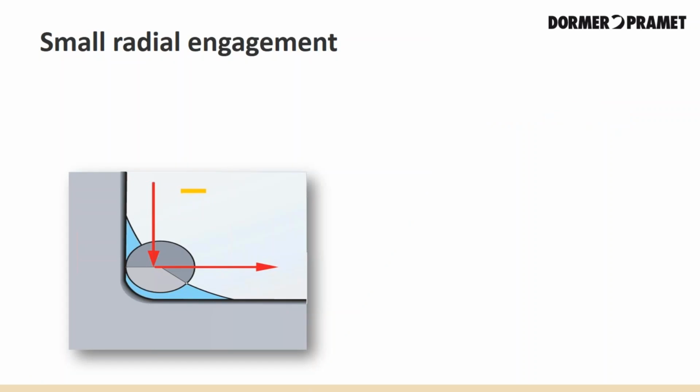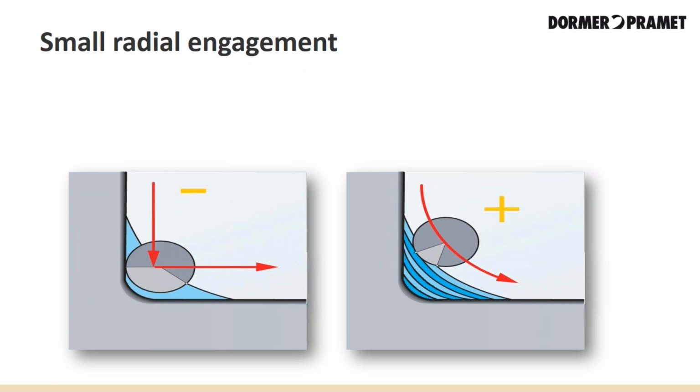The first picture is a common method. There's nothing wrong with this method, but it's giving you poor tool life and chatter in the corners. When you hear chirping, it will cost you money. Chirping is vibration, and vibration is loss of tool life. The second picture shows slice milling. Here we're using multiple passes to successfully remove the material using high-speed machining techniques with small radial engagements. The benefits are better tool life, lower cutting forces, and better finish on the component.